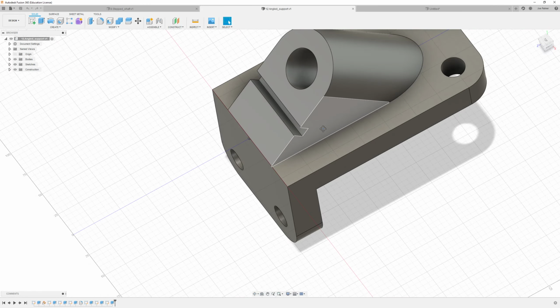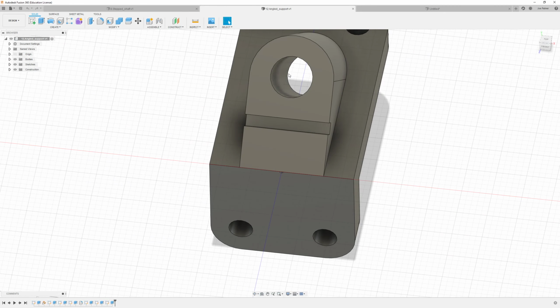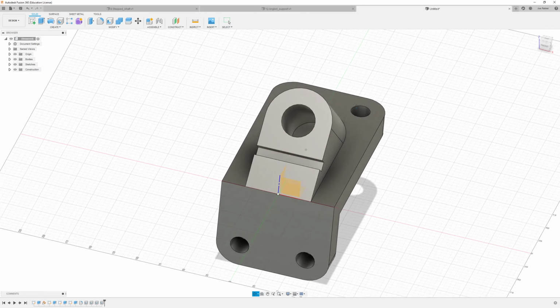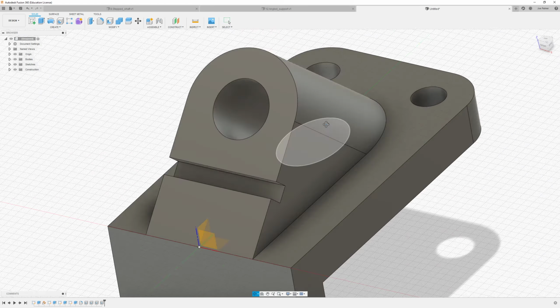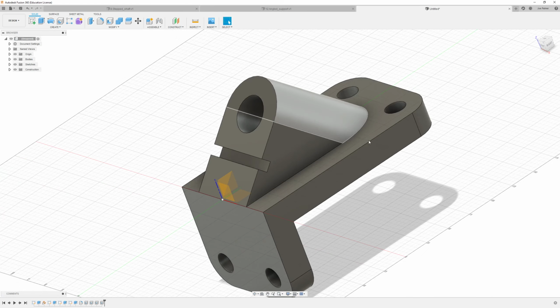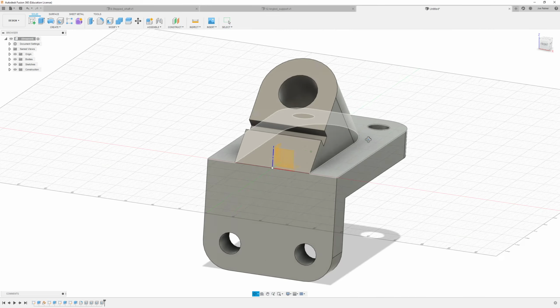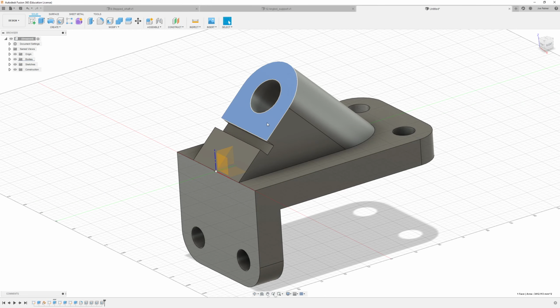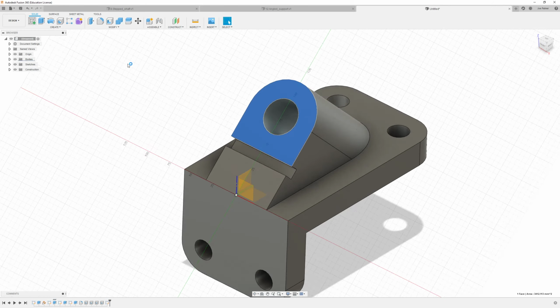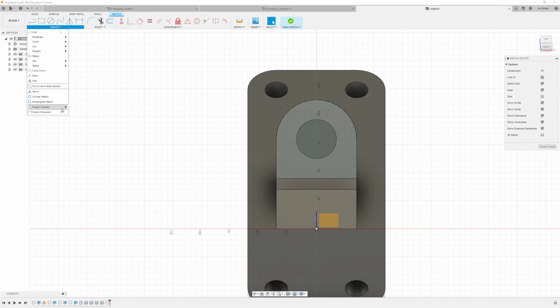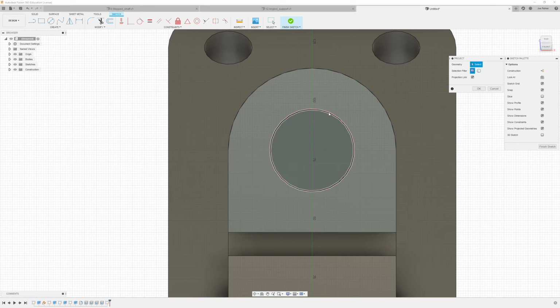I think the last thing that we actually need to sort out here is that the hole for the angled piece of geometry goes all the way through the component, whereas in the component that we've modeled, it does not, and that's because we extruded this original L-shaped piece of geometry before we created the angle section. So all we're going to do here is we're going to sketch on this front face of the component. We're going to project the edge for this hole that we've already created,